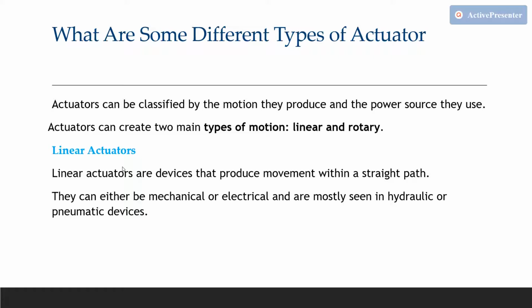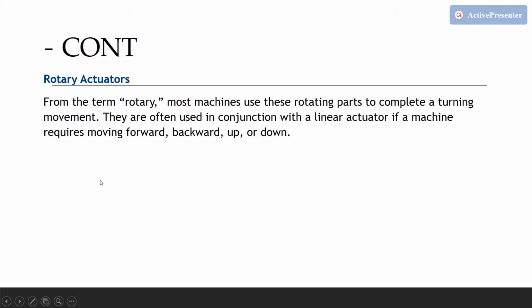The sliding tube provides the space for the motion, whereas the nut and the cover provide the interlocking movement that keeps the actuator in a straight path. The other complex linear actuators will have additional parts, obviously, but the system mentioned above is the foundation of the straight movement. So that is what we define as linear actuation.